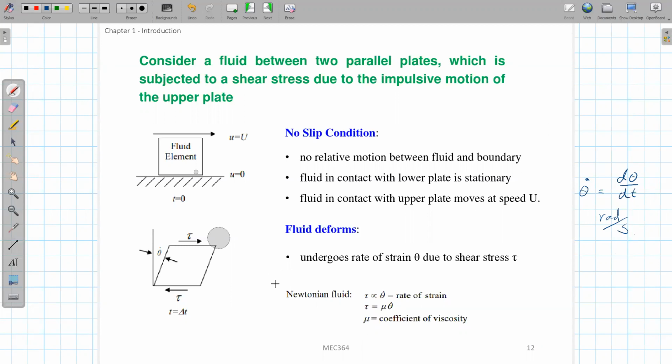And we will go through this later, but here is just a peek view of how we calculate the viscous force and the friction force here. So we can know that if it's a Newtonian fluid, the viscous force on the top will be proportional to this rate of strain. Okay, just to be careful about this term theta dot and theta. Okay, theta itself is the strain. It's showing how the strain will be, and theta dot is the rate of strain. So they are different things.